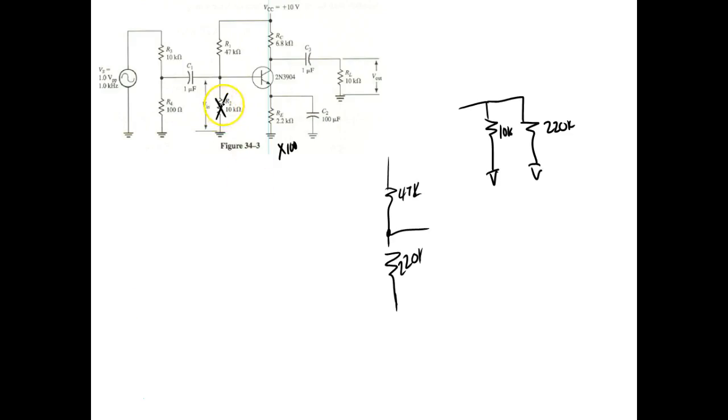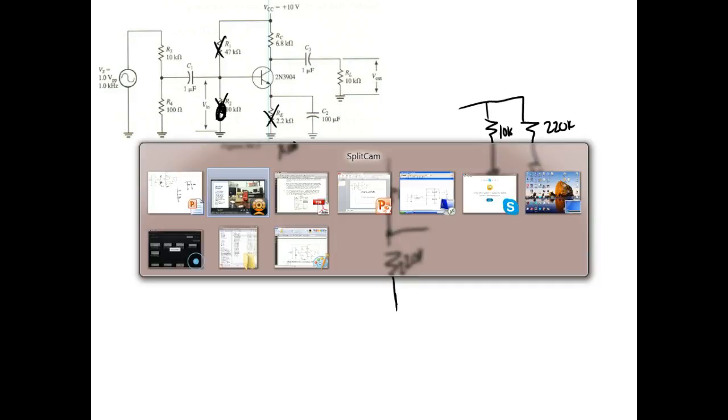So if this resistor opens up, the transistor saturates, your base bias voltage goes up, your emitter bias voltage goes up. If this resistor right here opens, then the transistor cuts off, right? You understand? Because that's what sets the base voltage. So you'd have almost 10 volts dropped across the transistor. If that one right there opens, we get some strange stuff which we won't get into. The base voltage goes way down low. And I think that's all the lab calls for, right?